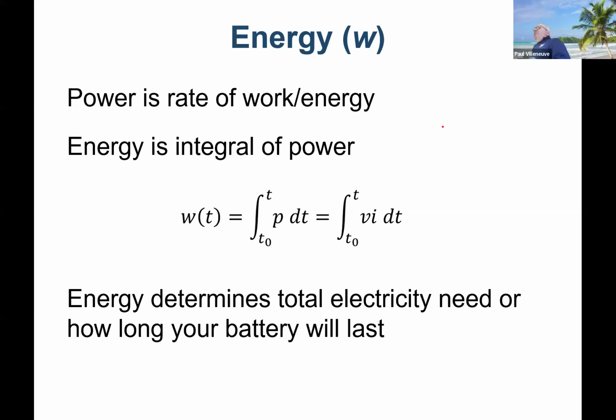So that is 100 horsepower, which we can convert to watts. How do you convert horsepower to watts? Multiply by 746 watts per horsepower, right? So you're almost at 75,000 watts, essentially. But the problem with that is that that's the rating. We actually want to know what the joules are, not the joules per second. So we have to take our power and integrate that over our period of time.